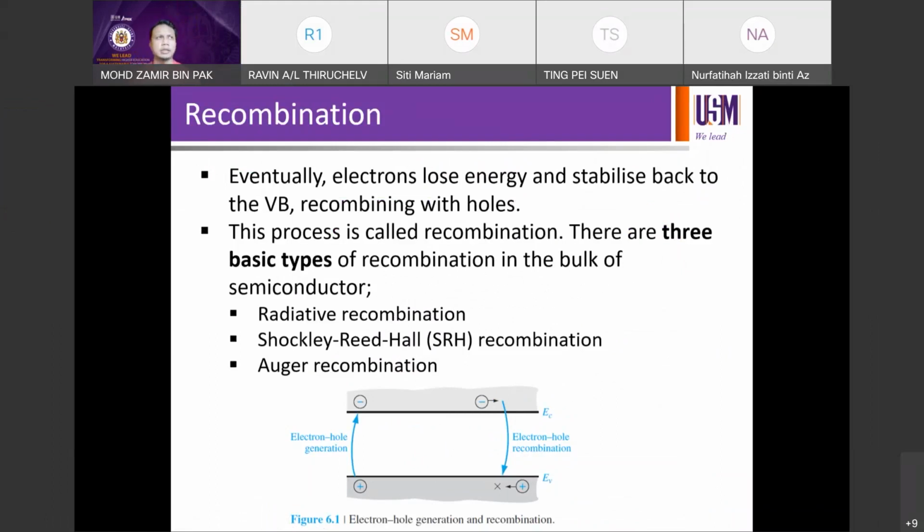Right, so in the last class, we learned about the concept of recombination. We learned that there are three types of recombination modes or mechanisms. The first is radiative recombination or band-to-band recombination. The second is Shockley-Read-Hall or SRH recombination, and the third is Auger recombination. And we discussed examples of when you have one or more types of recombination in your semiconductor materials or devices.